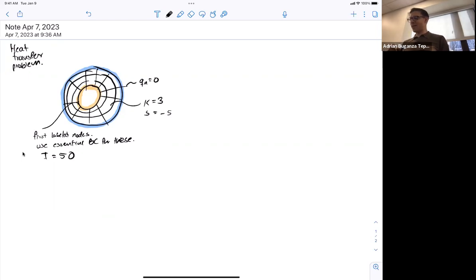Well, it doesn't matter. We still need to do Gauss quadrature. So -5 is okay. Because it's quadrilaterals, even if it's constant, we cannot just do the integral. We'll do it with Gauss quadrature. I'll actually change it. I'll do -5x. So it will be some positive. So there's a source term, but it changes from left to right. So -5x. Okay, so that is our problem, and that's what we need to solve. Find the temperature for that problem.